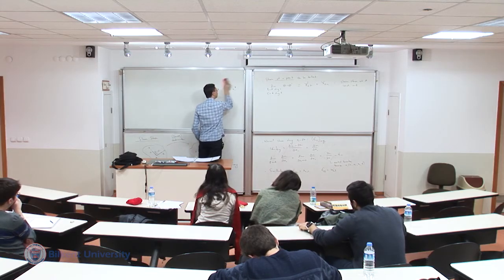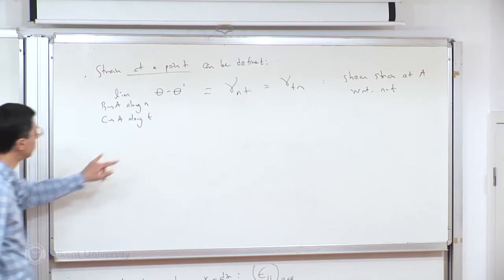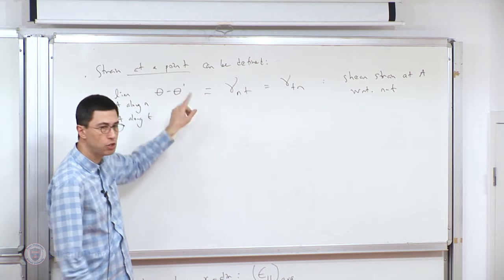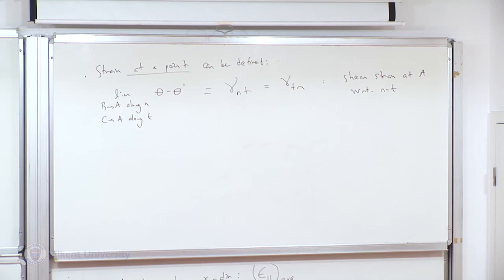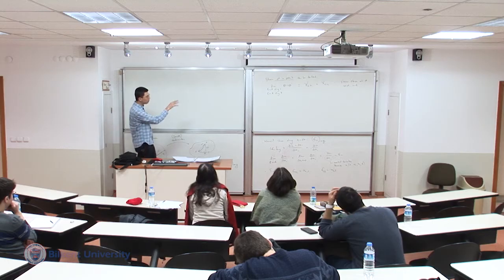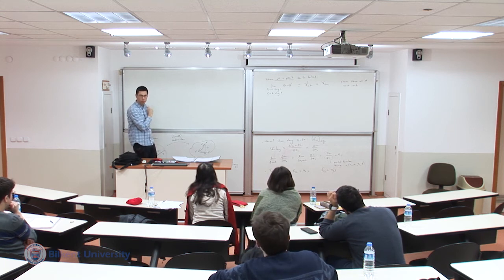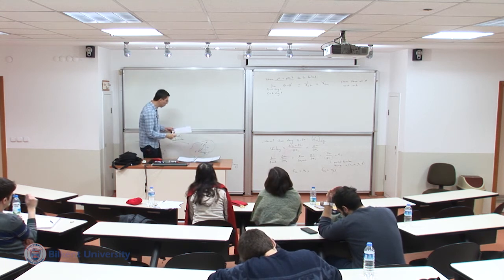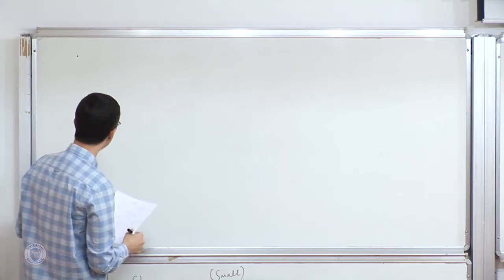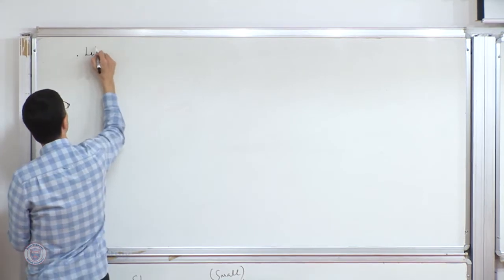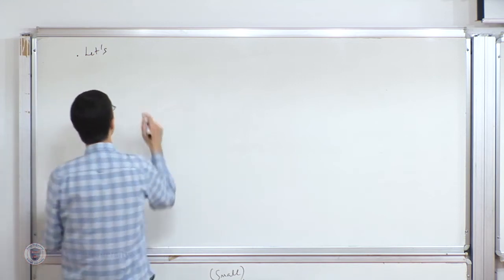We've got the 231 stuff out of the way. That's what we had used in 231. The major thing here is that shear strain has to do with change in the angle between the axes as the material deforms. The axes change the angle between them. Okay? So now we'd like to build upon that and link shear strain to the displacement field as we have done for the normal strain. And to make that not too mathematical, I want to build 3 examples that will indicate what that relation should be.